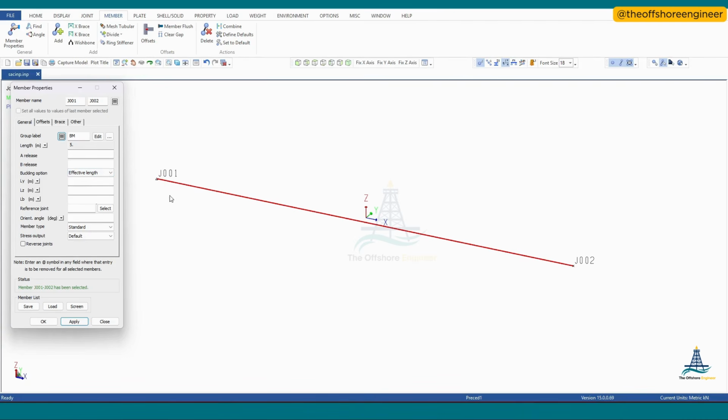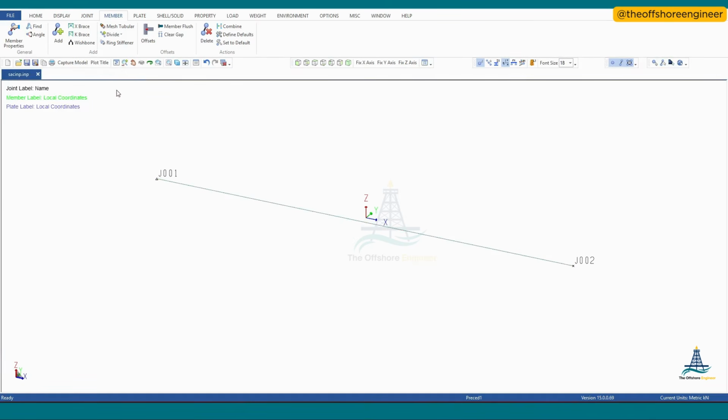So for this effective length, when the bending occurs in a plane perpendicular to the Y-axis, how will it be acting? This one will be like a cantilever, so the effective length will be twice the length of the beam. Similarly, when the bending happens about the Z axis, what should I give? It will also be twice because it's also a cantilever.